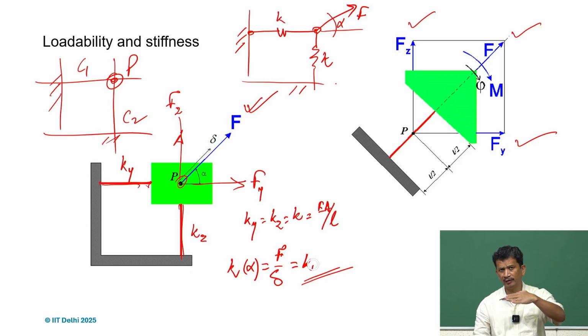So if we have just one flexure and a pure bending moment, then P will be halfway. If we put two identical ones, or in general any two constraints or flexures, the point of intersection will give you the instantaneous center of rotation. So it's not lying in between the flexures, but it's away.